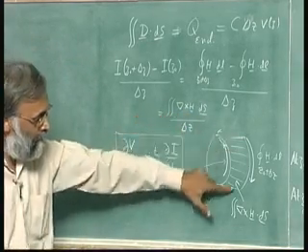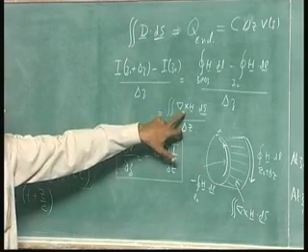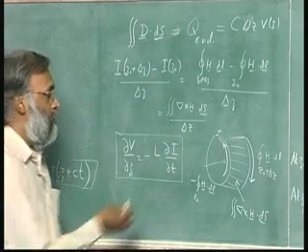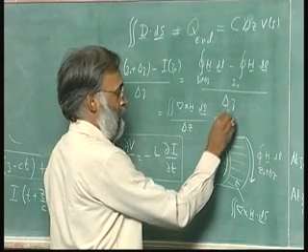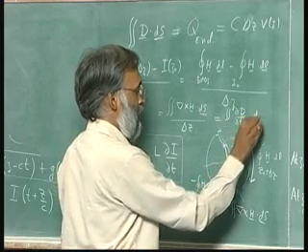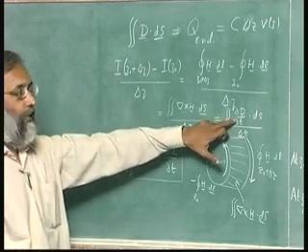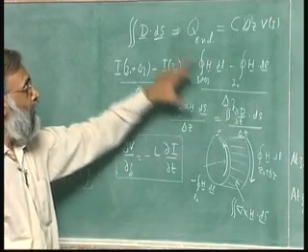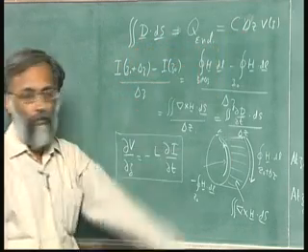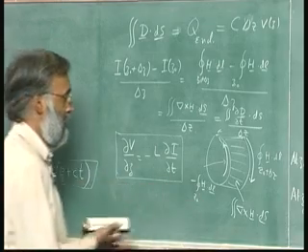This surface is the surface I have shaded as horizontal lines. Maxwell's equation is there now. There is no conduction current, all the conduction current is inside the wire. So this must be equal to surface integral of del d del t dot ds divided by delta z. I can pull that del del t out, and you can see that I already have d dot ds is C delta z V of z. So what do we get?